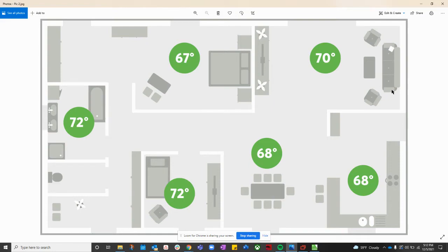What we want to do is create that perfect environment everywhere. However, let's say, for example, in this room it gets much, much lower than the rest of the house. The reason being is because the thermostat will end up being somewhere in the main area, where it's gathering an average of the temperature setting for that zone, and it can't really accommodate that room. So with that being said, we need to see what's going on in each room.